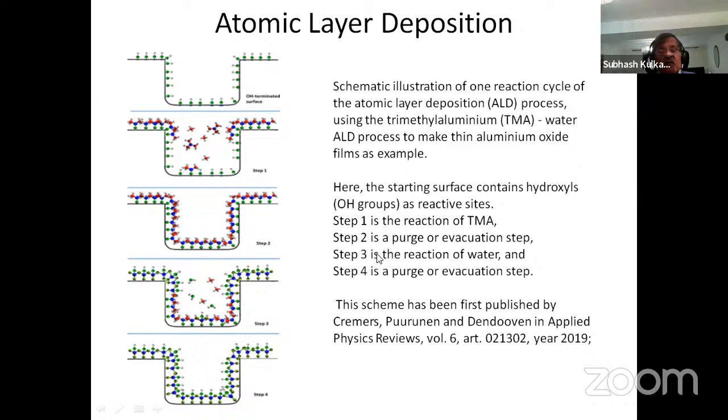Then you bring in another squirt of that material, and slowly, layer by layer, you get it to the actual thickness that you want. So this is really surface chemistry, very advanced surface chemistry under vacuum with very specific chemicals that are extremely high purity. And you form these layers, and then you get very thin layers that you need on the top of the topography that you have created. So this is called atomic layer deposition, because you are basically depositing atoms by atoms.